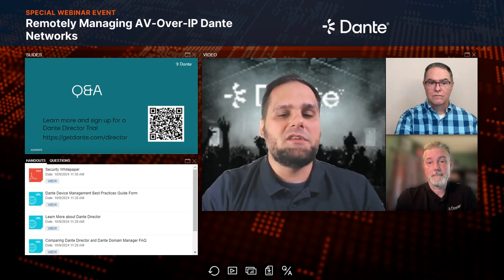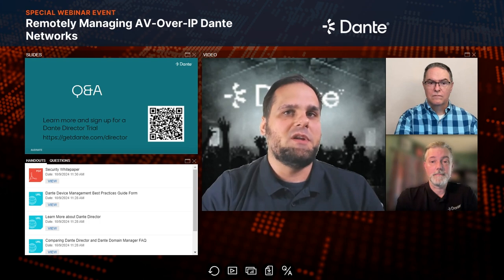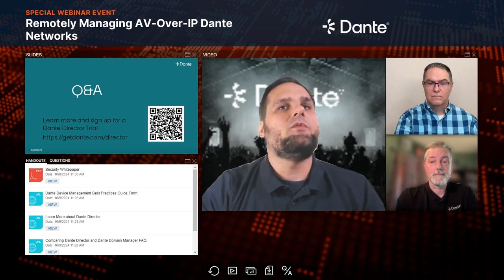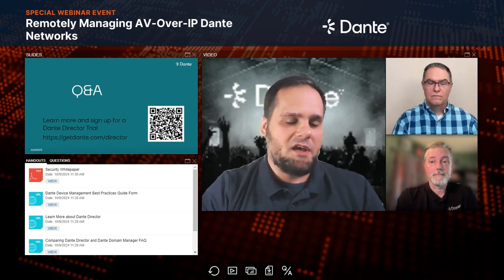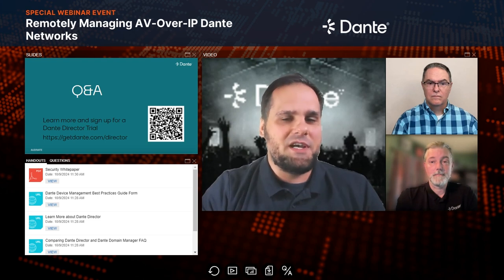But what we typically see with our end users who have particularly complex and distributed requirements where they actually want to route audio back and forth between networks in real time, then we start doing some applications with, again, what we call Dante Connect and Dante Domain Manager, where you would actually have a hardware clock at each site that is synced to a GPS satellite.